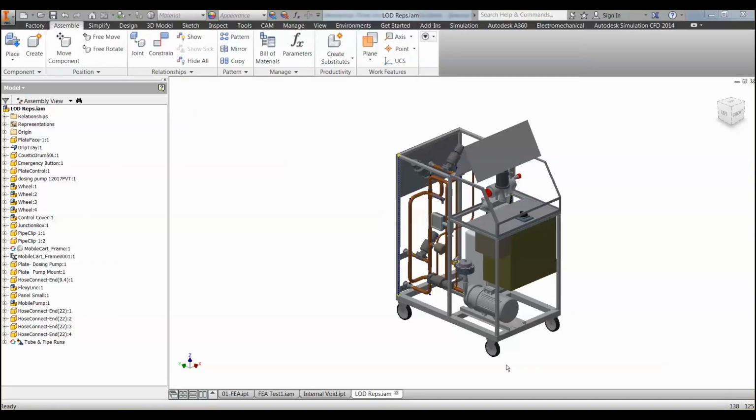Final thing I want to look at here is how we can manipulate assemblies to help with FEAs. First rule of thumb here is a production model is not the same thing as an FEA model. They may send you the assembly, but we don't want to touch the production side of it, because we might manipulate this thing for an FEA that's a little bit different than what they want with production. So we want to get this into our own environment.